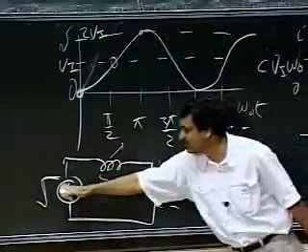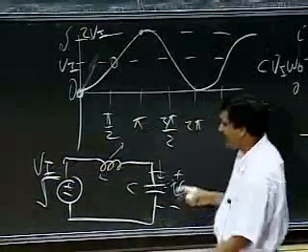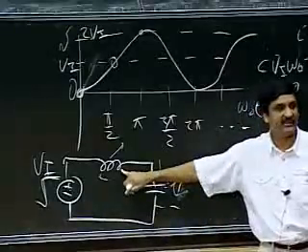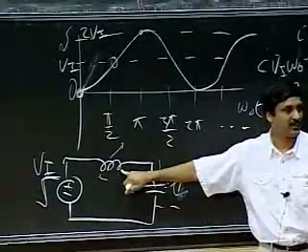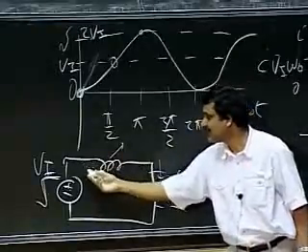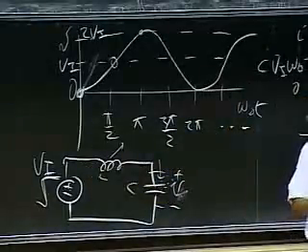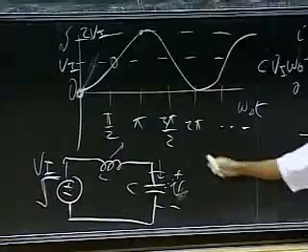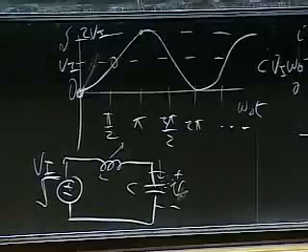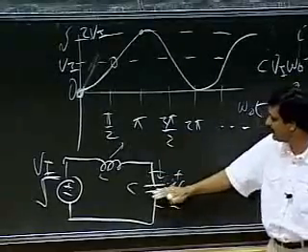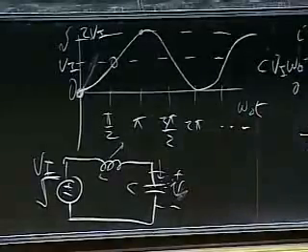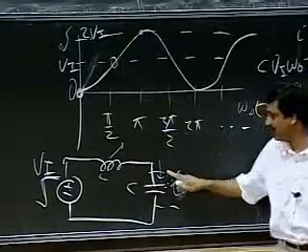But then VI equals this VI here. So when the two become VI, the inductor has 0 volts across it. So there's no longer a potential difference that's increasing the current in that direction. At pi divided by 2, I have some current going through the inductor. But there's no longer a pressure forcing more current through the inductor, because this voltage reaches VI.